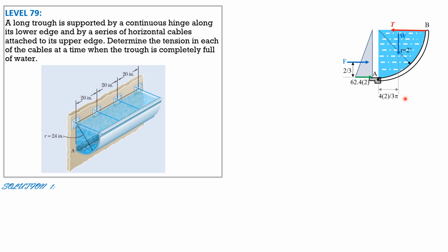But by principle, if we have a circular arc, the component forces can be replaced by a single force, which is the resultant, and the resultant passes through the center of this circular arc. So meaning we can move the components along the line of action of the resultant, so that the weight is no longer important.